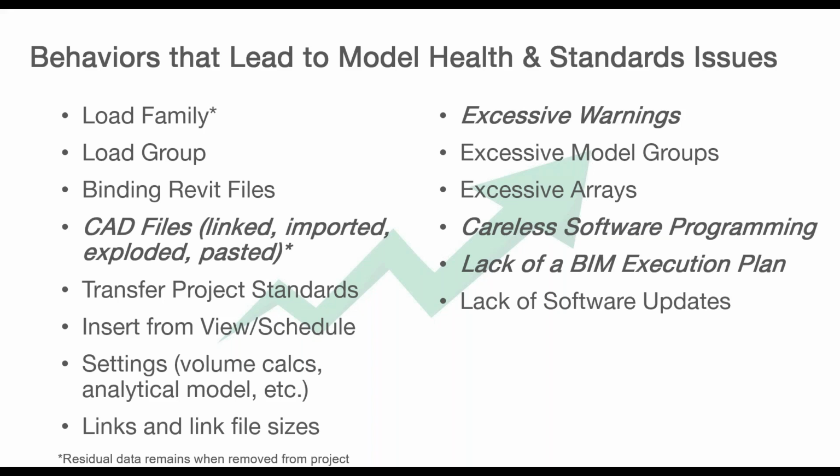binding Revit files, because again, kind of like the old AutoCAD days, when you bring something in and bind it, you're bringing in all that extra stuff with it. Have you vetted that file before you brought it in? CAD files. I can tell you CAD files, even if you link them, do bring in extra data that you may or may not have wanted.